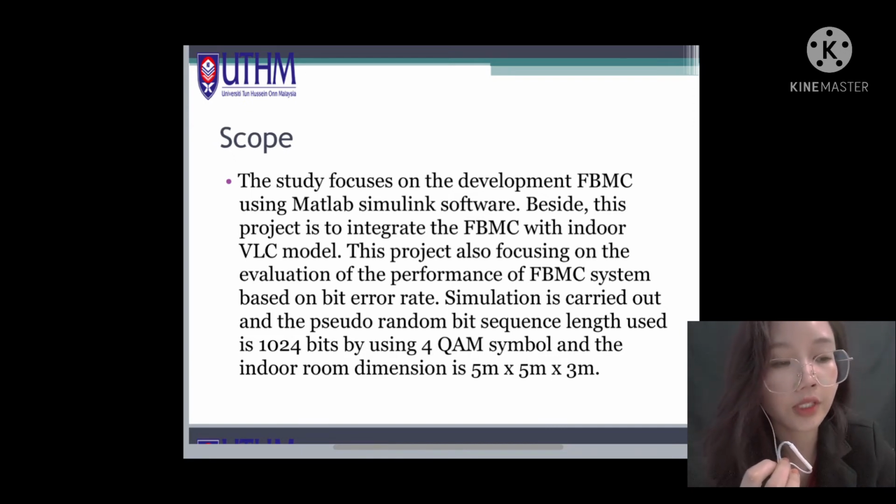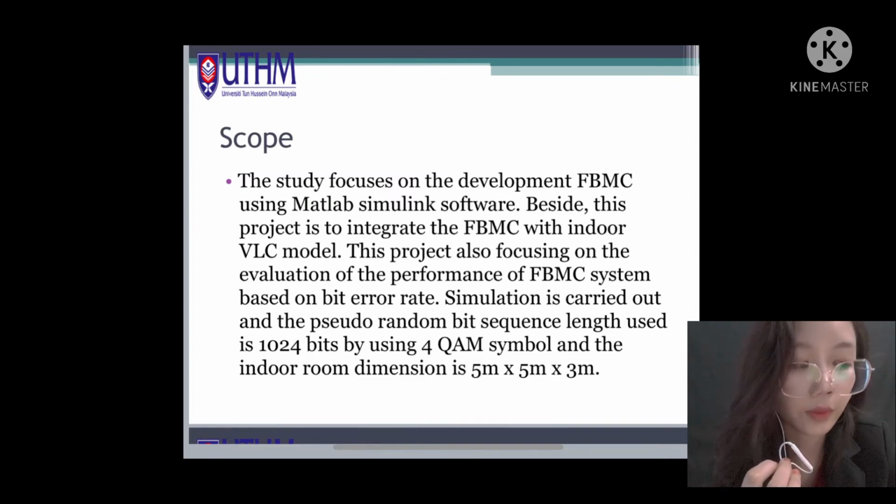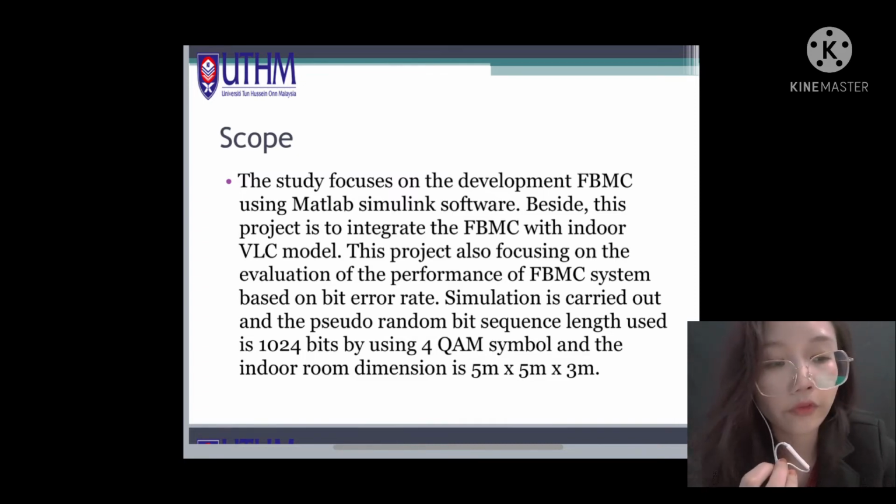The simulation is carried out with a pseudo random bit sequence length of 1024 bits using 4 QAM symbols, and the indoor room dimension is 5 meter by 5 meter by 3 meter. So this is the scope of the project.